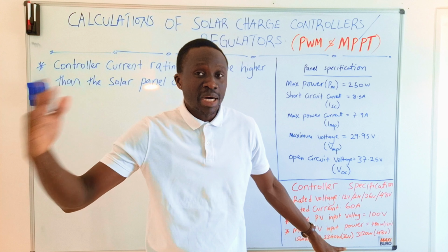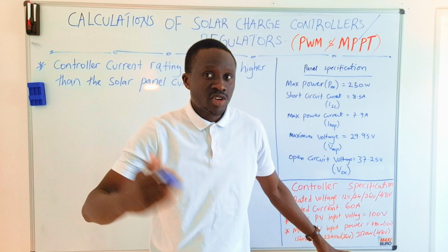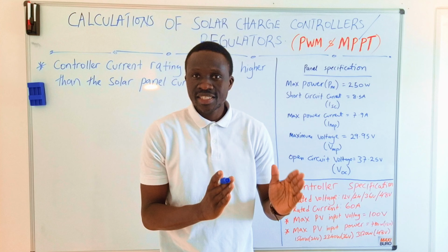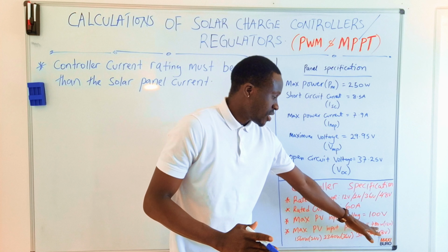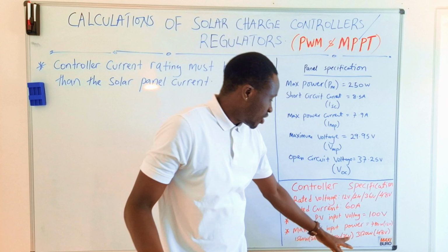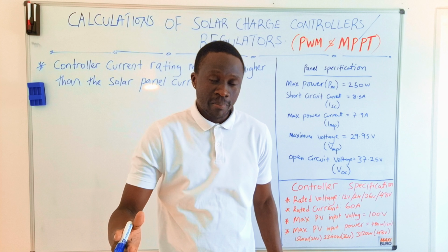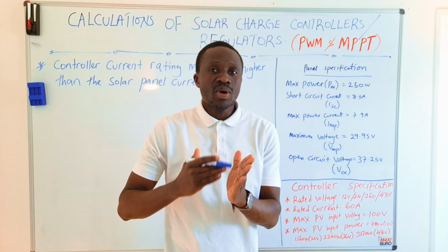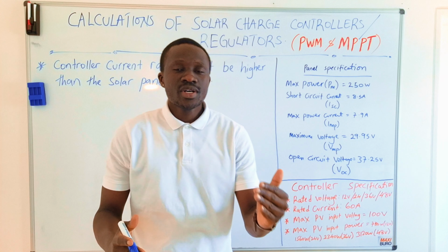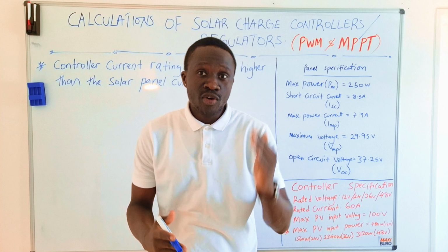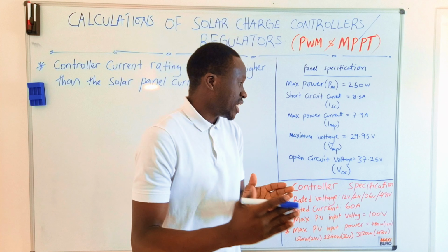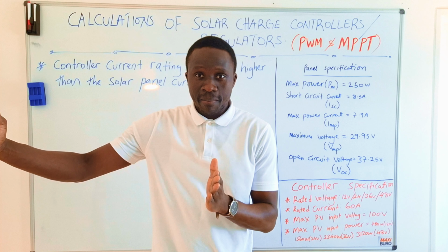12 volt battery. Okay, a 12 volt battery is always put on a system which is below 1000 watts. Then you can use a 24 volt battery on a system of more than 1000 watts. 24 is good. When you go to a 36 volt battery, the power from the panel must be more than 2000.